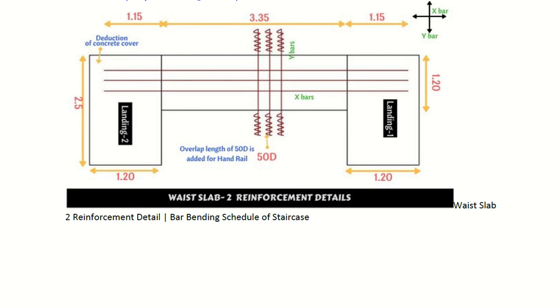The stairs go like this, right? So half of the landing is covered by this one, the other half is covered by this one. When you look at the plan view, it's only showing from the top, so you cannot see this one from the top. That's why you see half of the portion, it's not empty. It's covered by the other base slab. Clear?